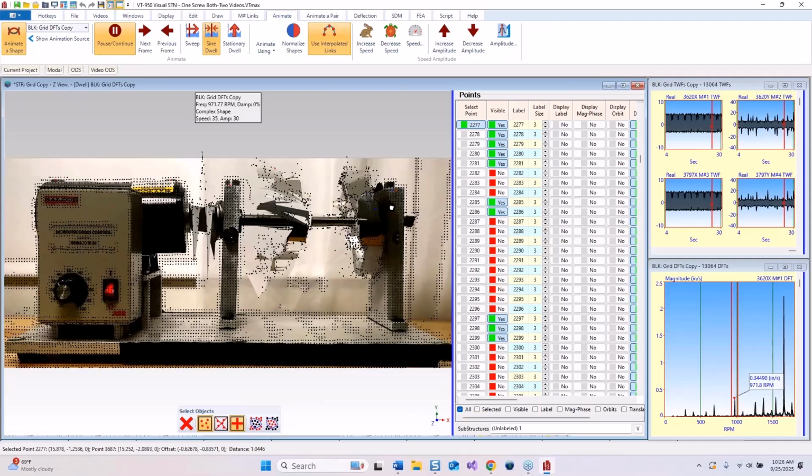Now I didn't like that one, so I'm going to click on it again. Oh, okay, I got some points that I didn't like there, so I'm going to just get one that's away from this rotor, because these points over here are going to be influenced in the algorithm by the motion of the pixels from that rotor. So let me just pick one over here a little bit out of the way, just to be on the safe side.